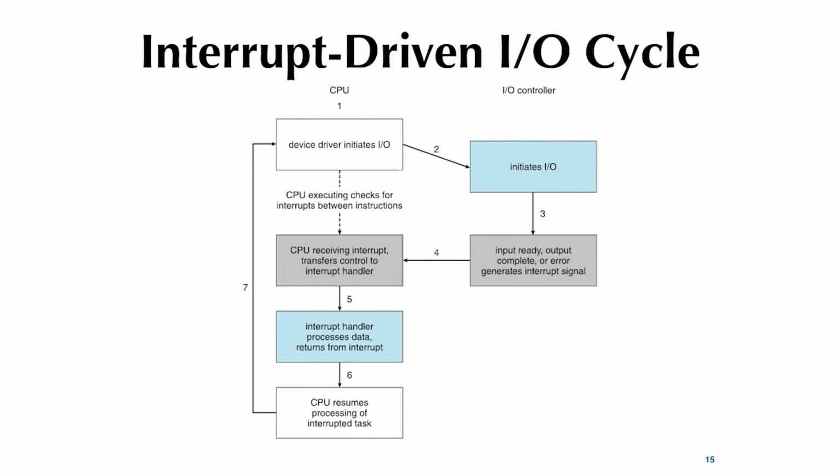So it may have to share that with some other devices. Then in the meantime, the CPU is doing its own thing, but then it gets the interrupt when the device sends that request, IRQ coming in, and the CPU then transfers control to the ISR. The ISR processes, returns, and then resumes. Right? But then, of course, the detail is all in there.